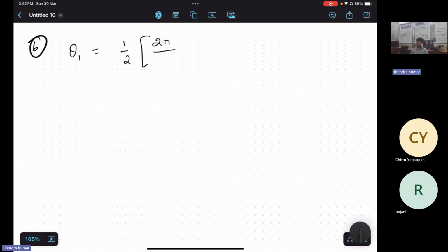2 pi by 4, that is the rotor pole pitch, right? Minus the stator pole arc plus rotor pole arc. How much is that in radian, or even in angle? If the angle is mentioned as 20 and 22, we will take that directly. I have converted to radian and calculated, sir.